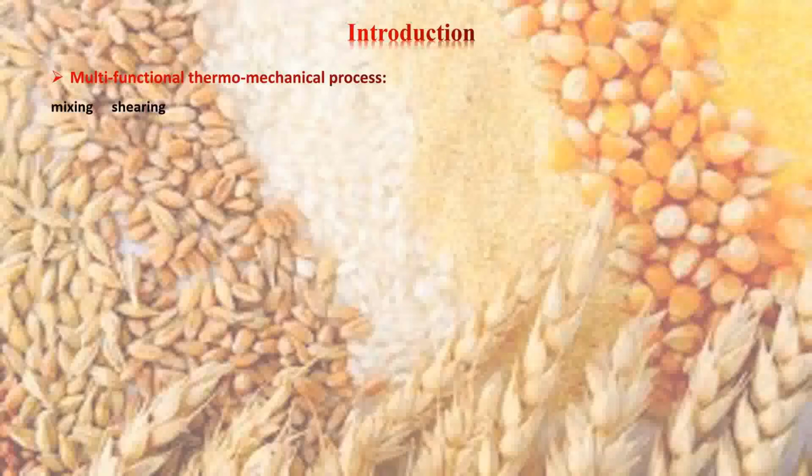So this shearing is nothing but that particular thing which happens to food material within the extrusion chamber. And after that we have heating. Heating means addition of external heat, or the heat developed within the extrusion chamber due to the increase in extreme pressure, which helps in melting the premixed ingredients and converting complex molecular chemistry into simpler forms that can be consumed and digested by human beings as well as animals.